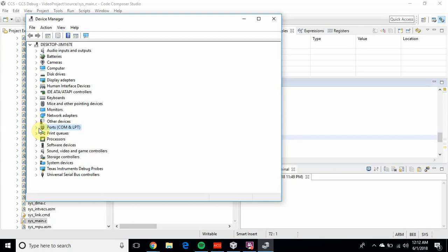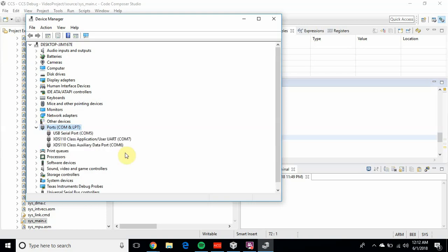So the USB that you've plugged in via the breakout board is going to be recognized as a COM port, communications port, that then your computer will read information from. As you can see here, I have 3 listed, and these are all actually from the board. I'm just going to explain them top to bottom. The reason we have you guys setting up this external USB to UART breakout board is because our actual OBCs don't have that nice little internal debugger where we can just plug USB in and use everything for that. We need to be using these external hardware pieces that plug onto the OBC because we don't have necessarily all those niceties inside of our board.